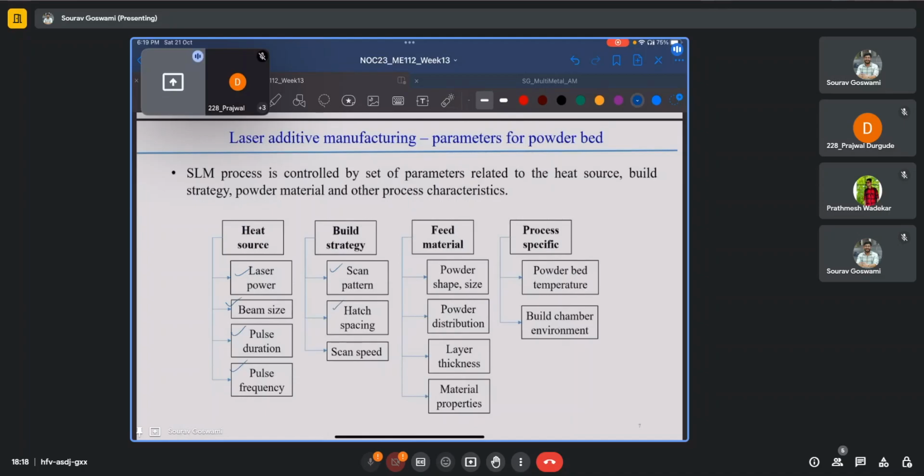If we remember, in the case of metal inert gas or gas metal arc welding based additive processes, it has been shown to be equivalent to two-thirds of the bead width. So the ideal hatch spacing or pitch P was equal to two-thirds of the individual bead width for a multi-track deposition in the same plane, and this would provide the flattest surface or the best surface finish.